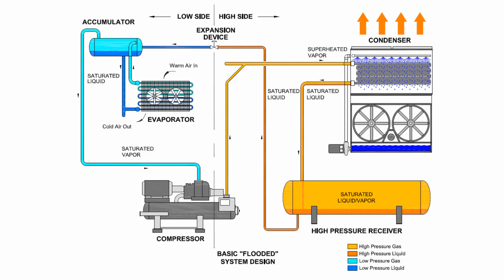The purpose of the compressors is to raise the temperature and pressure of the low-pressure gas in order to reject the heat absorbed in the evaporator to the atmosphere. The compressors receive low-pressure vapor from the main suction accumulator or recirculator and discharge high-pressure vapor to the evaporative condensers. Under normal conditions, the compressors contain both high and low-pressure vapor ammonia.